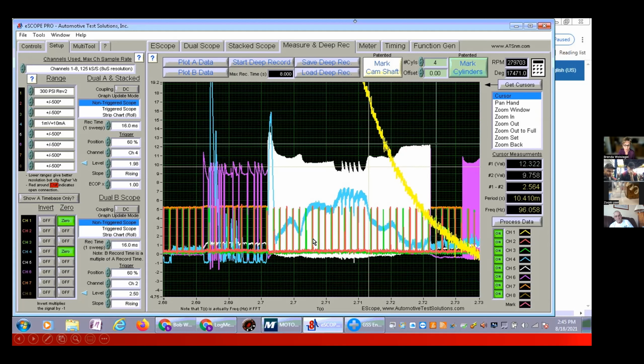But now, if we understand that this is representing a zero current test on the motor for leakage, it turns the phase on. We get a very high spike in current, okay, as we did over here with the purple. And then as the phase is applied, it rises and rises and rises. It does this jiggy thing and it falls.